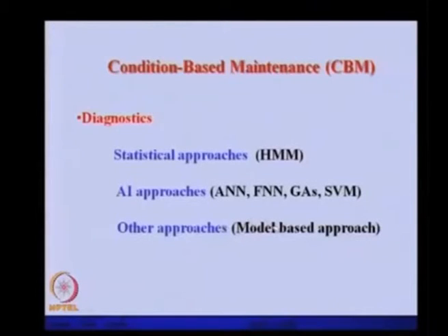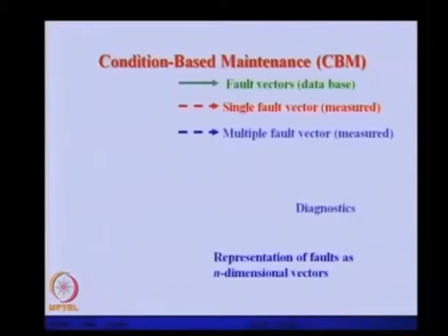And once we measure the vibration from the actual system, we can curve fit the mathematical model with the vibration signal and try to find out whether the fault is there, and if it is there, how severe it is. The quantification of the fault we can do with the model based approach, which is real research taking place at present in the rotor dynamics field. So, this is a very abstract way of how we can diagnose the fault.